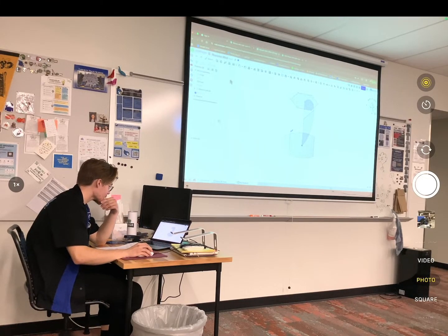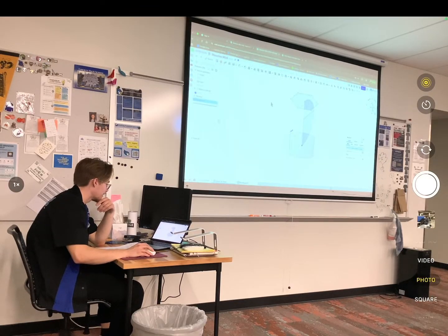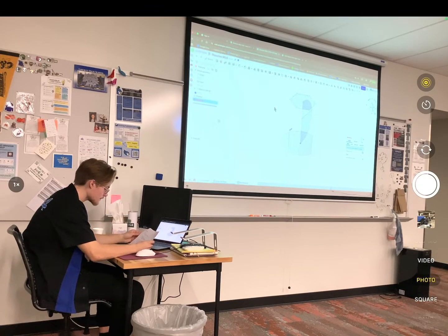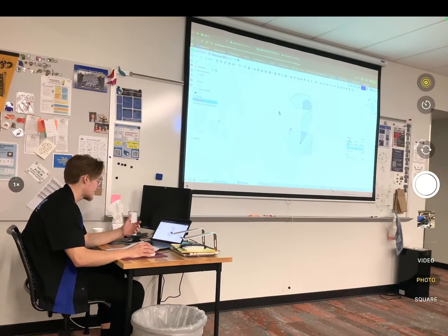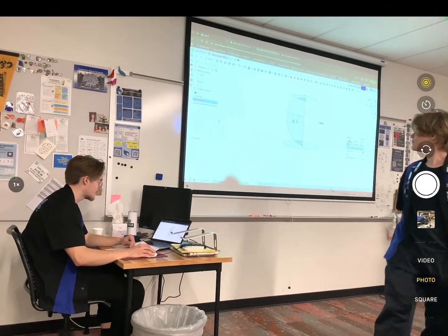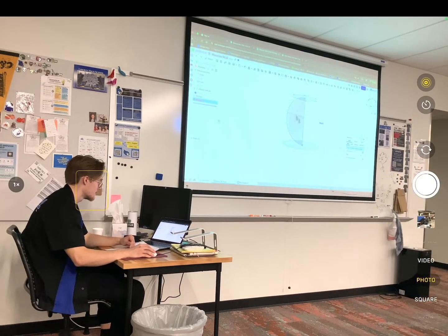Okay. So for the revolve tool up here, to the right of the extrusion, instead of a normal extrusion, what it's going to do is a rotated extrusion instead of being a linear one. So, number 1 with the revolve here, what I'm going to do is again select my entities, or my sketch, that I want to be revolved. You guys don't have to follow along, by the way.